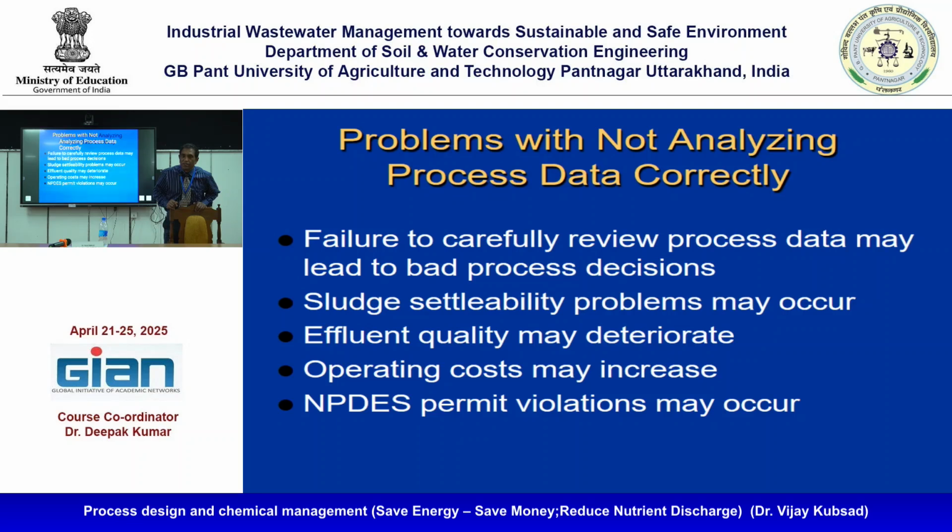If your source in the industry is groundwater, that is a different problem. It has a TDS already. How much TDS? If you are not aware, you are using that water. He said, what is the source of your water? Groundwater. Yesterday you had been there. What was the source? Groundwater. So we are taking groundwater and treating all that. But have you analyzed what the TDS is at the source?